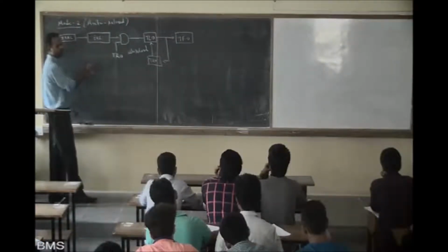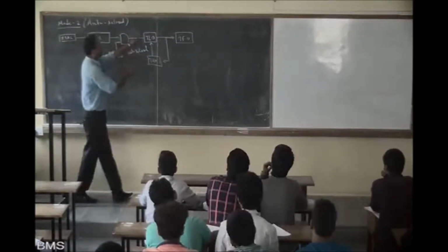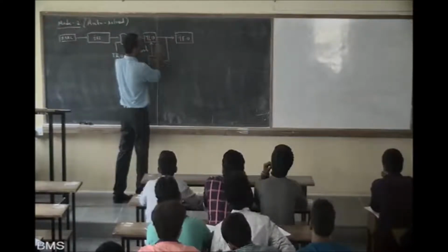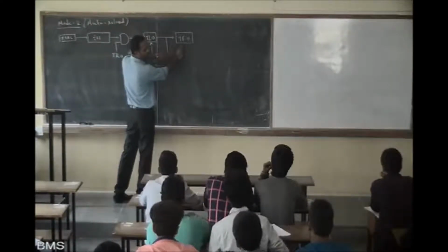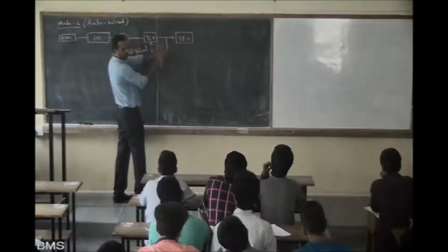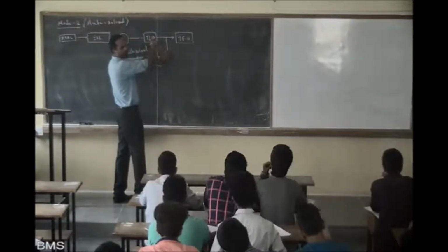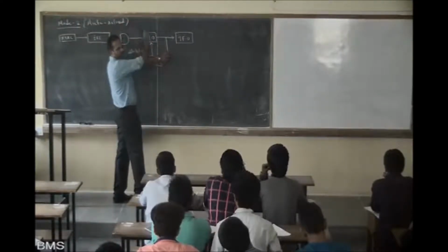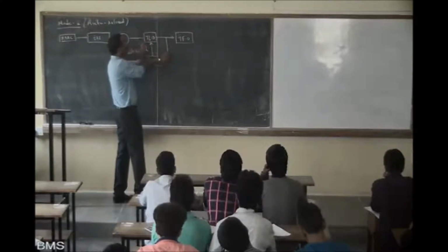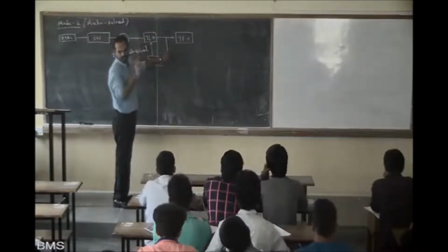Is it right? So it is very similar to mode 1. In mode 1 we had TH0, TL0 connected to TF0. We don't have this part. It just used to count this. Depending on the signal here, it starts counting here. Now if you give a signal, only TL0 will start counting.